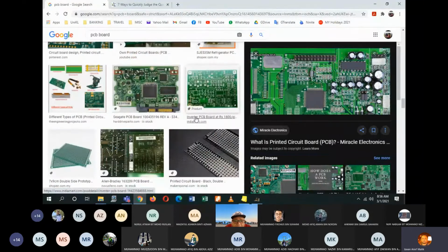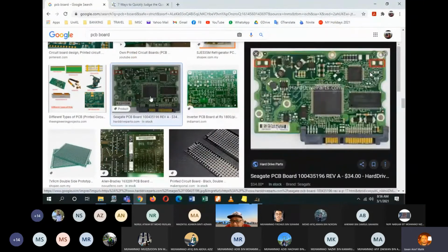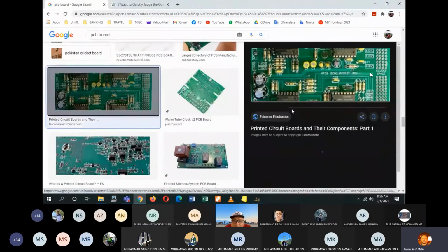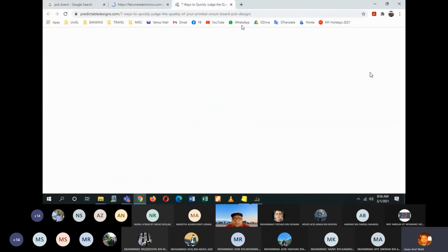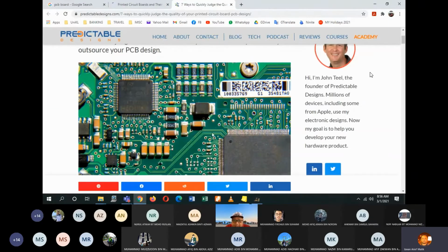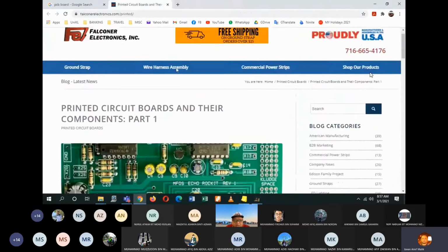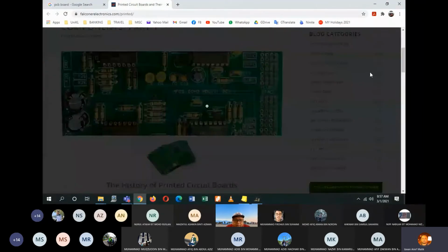Through holes. SMT juga. Saya nak tengok yang semua through hole. Okay, inilah. The part here dekat sini dia pakai through hole, means that pin through hole components, and then the rest here you tengok dia pakai SMT, yang tak perlu tebuk lubang. No holes drilled through your board. Normal resistors ni, yang ini through hole, yang ini semua pakai SMT. So saya tak nak tunjuk itu. Yang ni lah, okay. This one is better.